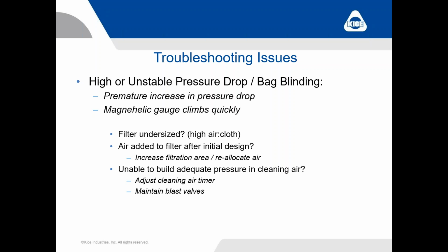There's a pressure gauge. We can push that little black thumb button and read the pressure in our air tank. And we know on our high pressure cleaning system, again, 80 to 100 psi is what we're after. If you look at that gauge and it's never climbing above 20 or 25 psi, perhaps we have a leak somewhere, we're not able to build pressure.